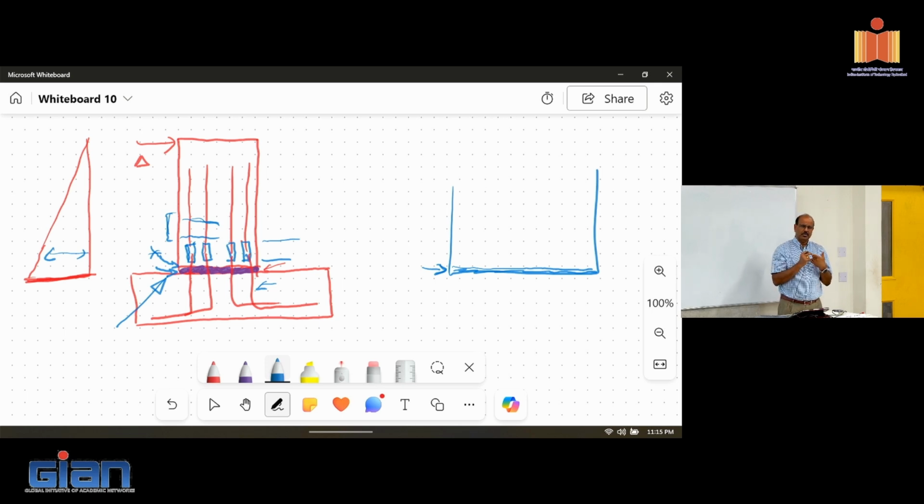But I want you to remember that in each case, because the wall could potentially have different strengths, we are evaluating all of the walls under displacement control, right? Meaning that we continue to increase the displacement so that the wall can fail at any time. But as you increase it, your moment gradient, moment is going to increase, and therefore the strain is going to increase, the penetration effect is going to increase, and all of that will be reflected.